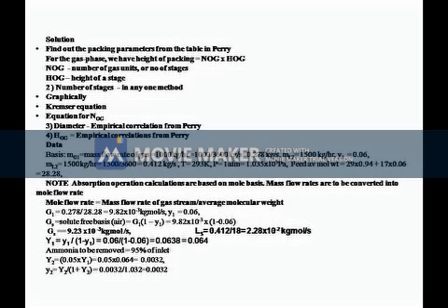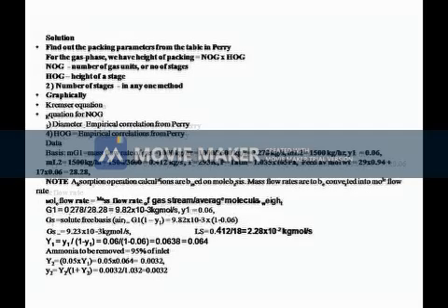Even though we say it is pure, we will not be able to remove all the ammonia. So Y2 is the mole fraction of solute in the gas going out of the column, and L2 is the liquid, here water solvent, which is fed into the column, and X2 is the concentration of ammonia.